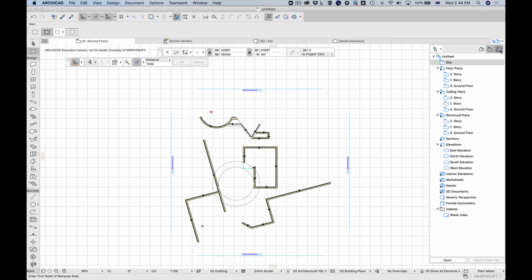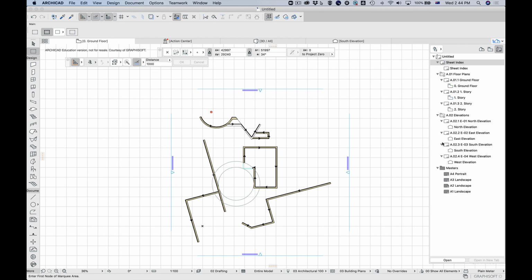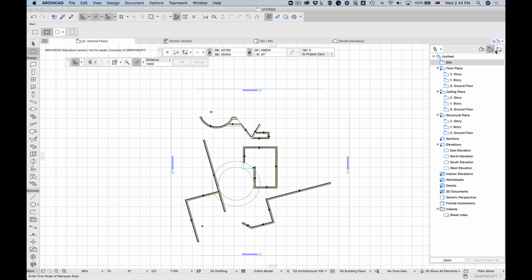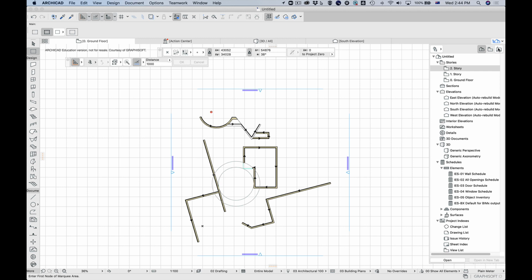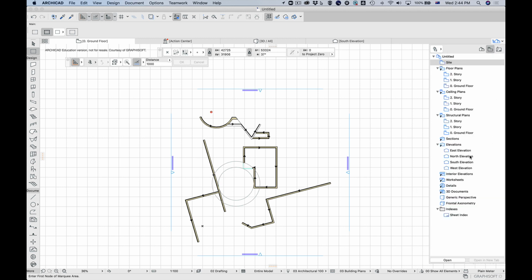That last one we'll do in another session. Those are our layouts. This is like AutoCAD's version, which is called paper space. So we can save views and then drop those saved views onto layouts. We can actually grab these and drop them straight onto a layout as well, but the saved views will store a whole bunch of information, and they're really handy just for organizing your drawing.